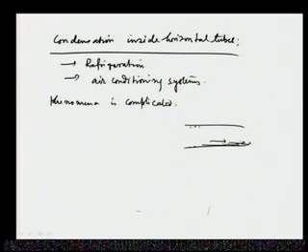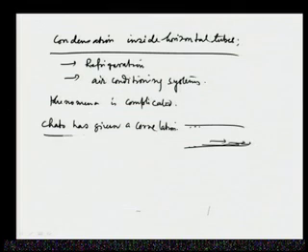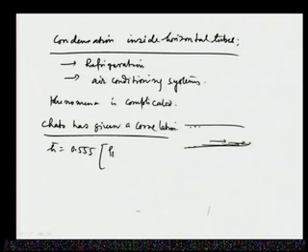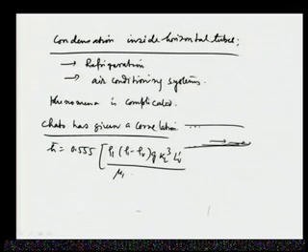Now, as we understand, this condensation phenomenon is a bit complicated in a horizontal tube, so theoretical analysis becomes difficult, but Chato has given a correlation where h bar is equal to 0.555 times [rho_L minus rho_V times g times k_L cubed times h_fg dashed over mu_L times D times (T_infinity minus T_W)] whole to the power 1/4. Here D is the inner diameter of the tube, because it is happening inside.